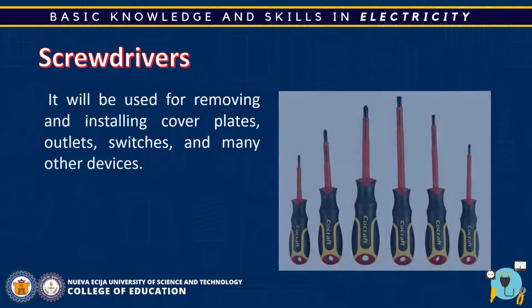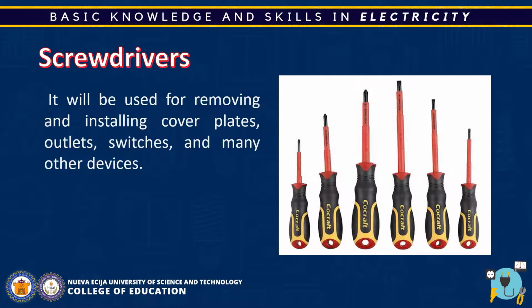Screwdrivers. Electricians keep screwdrivers with them at all times for removing and installing cover plates, outlets, switches, and many other devices. It's best to have a few different lengths of Phillips screwdrivers. Screwdrivers with insulating rubber jackets covering the handles are designed for better safety when doing electrical work.